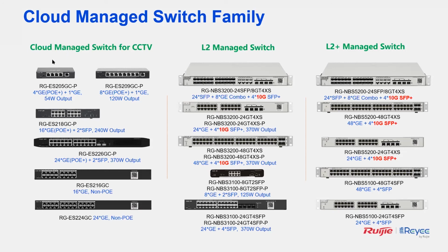For CCTV projects, I propose using the ES200 because they don't have many features, so the cost will be cheaper compared to other switches. But the features are enough for the project, like long distance transmission, remote reboot helper, and camera recognition. And we have 5-port PoE, 9-port PoE. With 16 ports, we have 2 options, PoE and non-PoE. Also 24-port PoE and 24-port non-PoE.